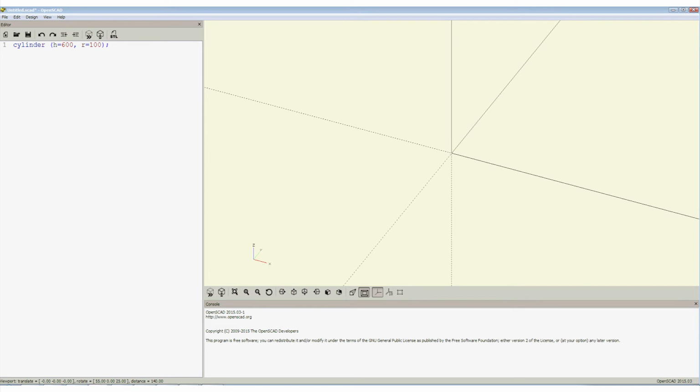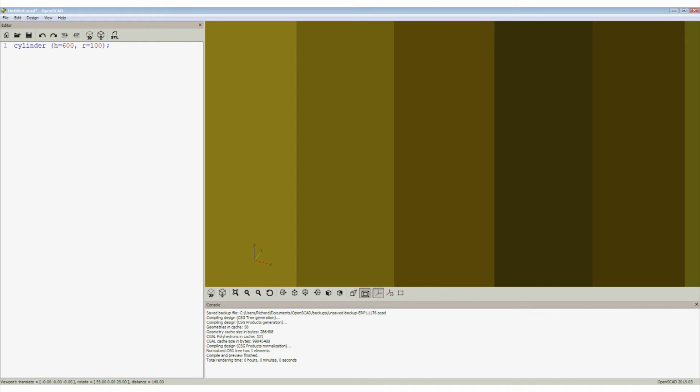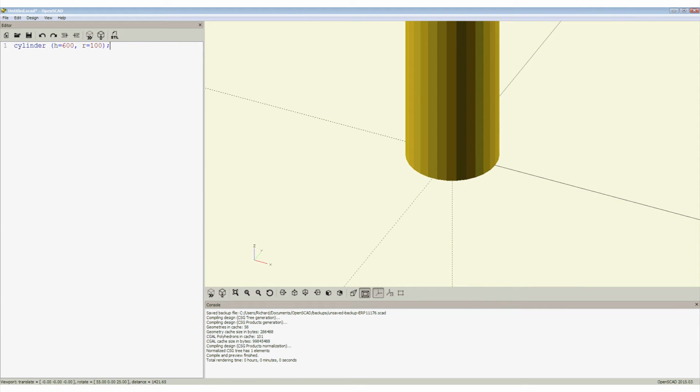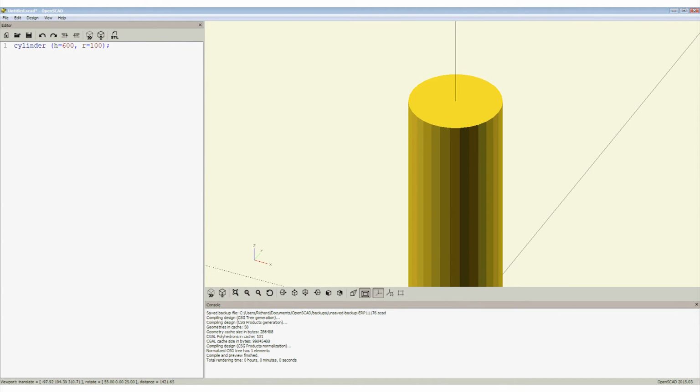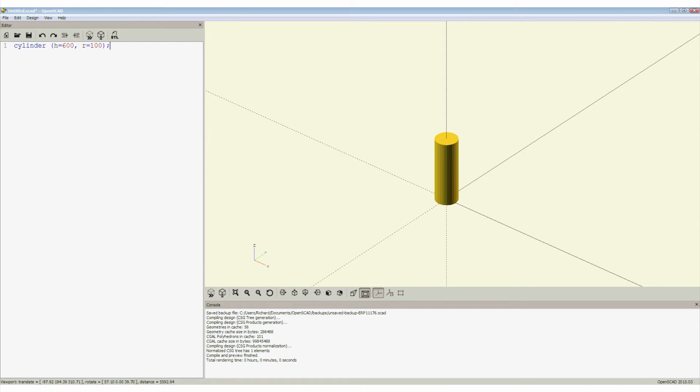In this section, we will follow a design process as an introduction as to how programmable OpenSCAD is, and how functions normally seen in software come alive as they're demonstrated in this 3D environment. We will try to build a column as a working example. We can start with a cylinder. Choose any size, say height 600, radius 10.